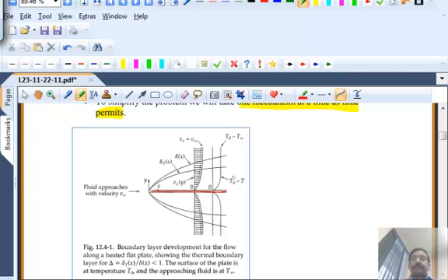So there are two boundary layer thicknesses that are shown. This one is the delta, which is the momentum, and this one is labeled as delta T, that is the thermal or the heat boundary layer. So for example, if you look at the velocity field, it changes in the boundary layer, and then it becomes constant outside of it. And if you look at the temperature field, it changes like this, and then it becomes constant outside. So what we are saying is that there are two small regions, one which confines the momentum diffusivity, the other one that confines the heat diffusivity or the heat conduction.